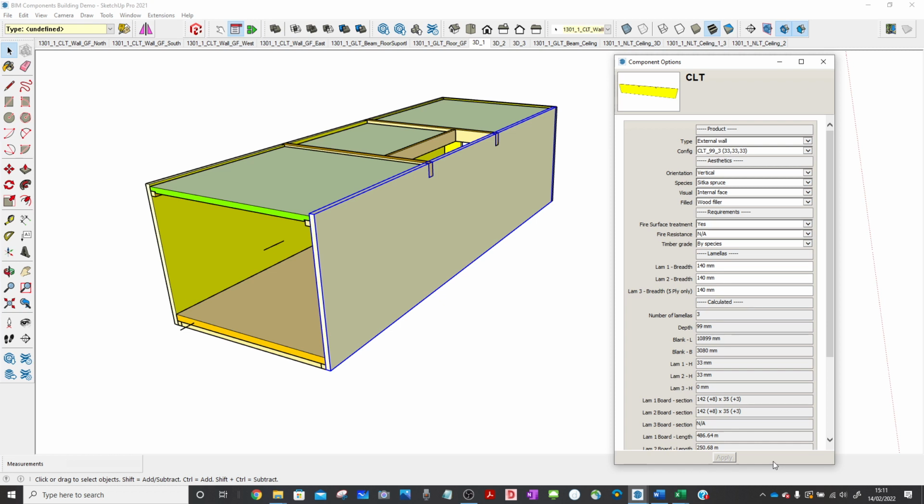So if you've got a 3 lamella system, you would put boards down, then glue on top of the boards, then put another layer but rotate it 90 degrees, then put boards down, then glue again, then put more boards down. That would be the simplest form, a 3 lamella or 3 layer system. Cross laminated timber is becoming very fashionable at the moment. You'll see it all over Europe.